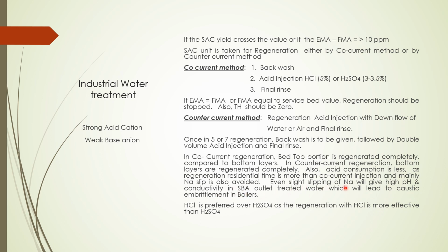The sodium slip will occur in co-current regeneration. It will not occur in counter-current regeneration. HCl is also preferred over sulfuric acid as regeneration with HCl is more effective than with H2SO4.